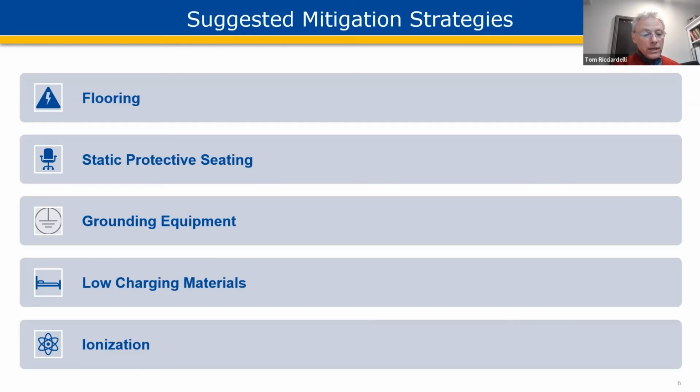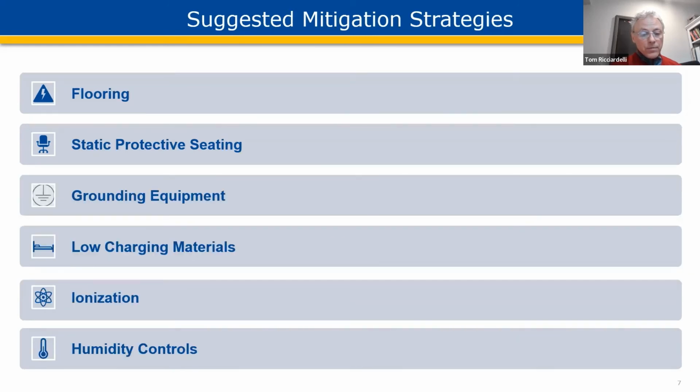Another area where an ionizer can be very effective is, a lot of medical devices are packaged in plastic packaging. When you open that packaging, you're actually generating a fair amount of static charge. If an ionizer is implemented at the point where that packaging is opened, you can neutralize that charge. So there are some places where it can be used. It's currently not highly used in healthcare environments, but it does have some very specific and very useful applications.